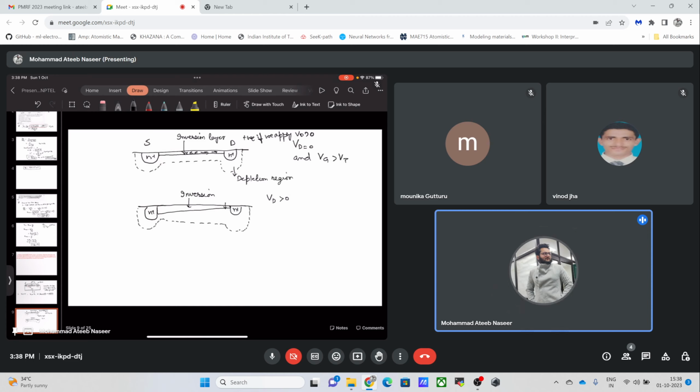Now after this, if we continue to increase this bias, you must have seen in the lectures that this channel will pinch off inside the device, and we will be having something like this. This is the N plus region. We will be having it like this. The channel will be pinched off. There will be no carriers at this point.